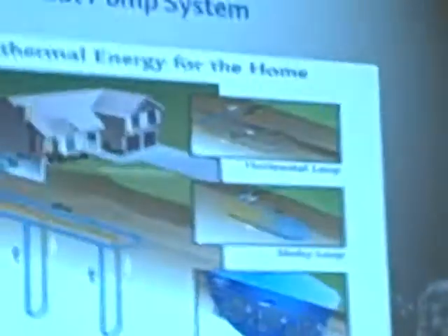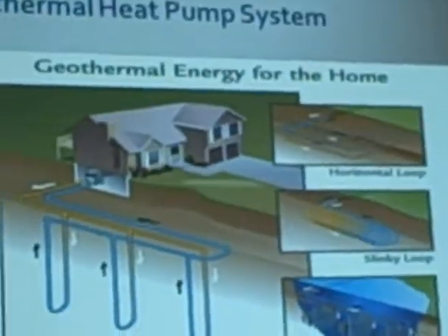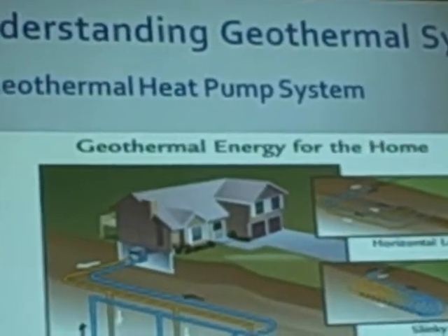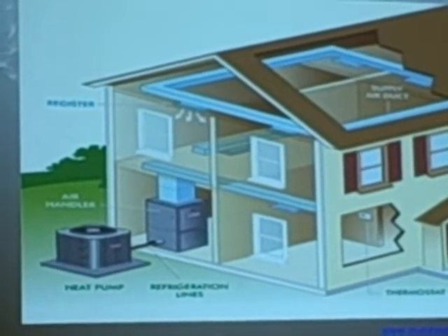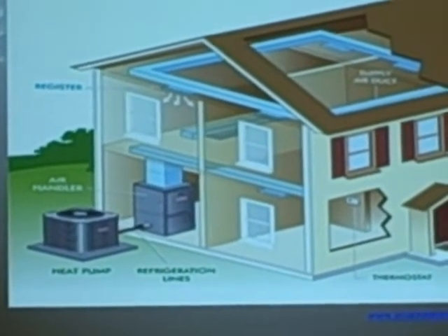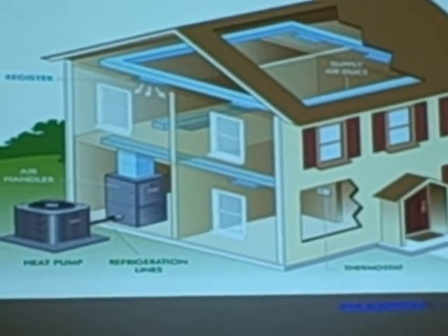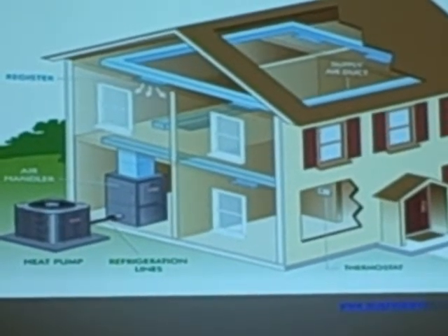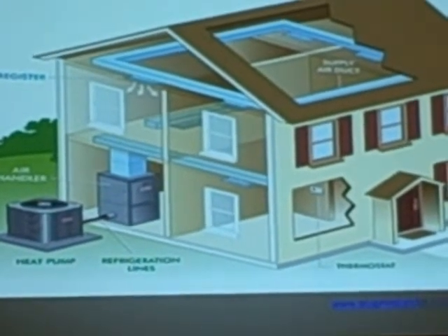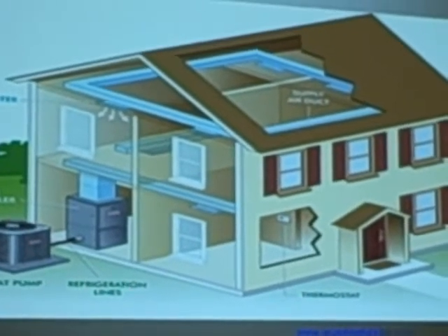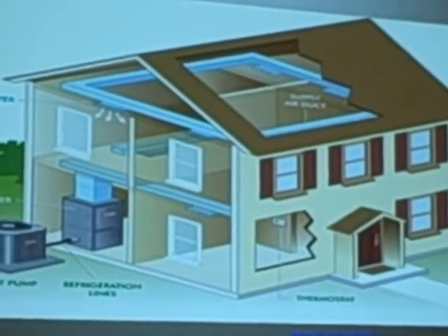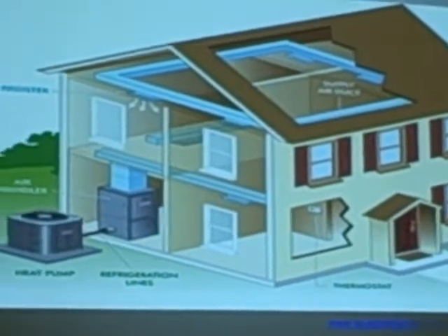In a geothermal system, we basically take that same home, and now we put the compressor inside the house unit, and we put a pump on it, and we just wash the water through a geothermal well field. Okay, so this condensing unit, this unit here, if I would simply unravel the outside of it and lay the coils out and bury them into the ground, and I could get enough heat exchange surface off of them, I would have a geothermal system at that point. All I'm trying to do is get rid of the heat and get rid of the cold. In most environments, we just put a big fan across it, taking energy, and force the air across it so we can force the heating and cooling effect.